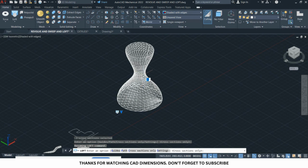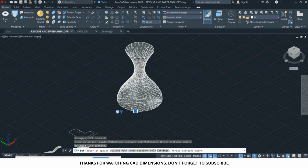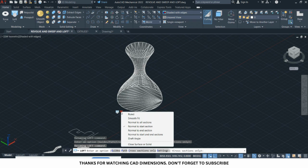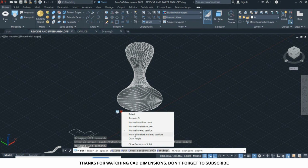Then we have the normal to the start section, so the first one will be normal, the others wouldn't. Then we have normal to end section, so the last circle that you selected would be the one that is normal.